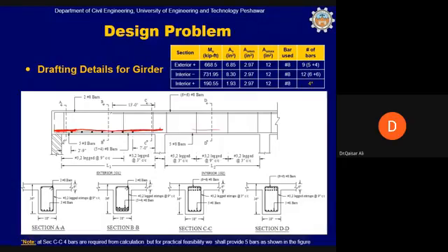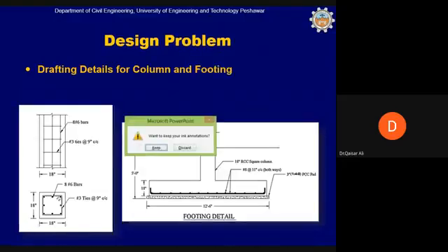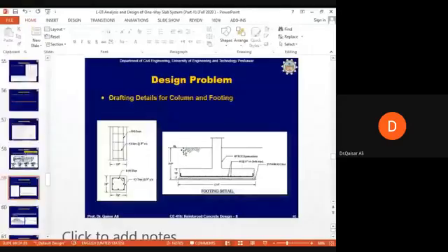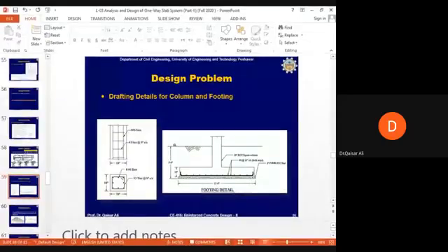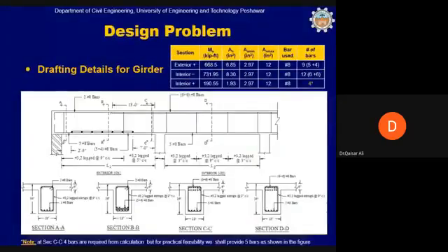of the bending moment. So if you take section BB, in section BB you can see all the positive reinforcement. You have 1, 2, 3, 4, 5, 6 plus 4, 10 bars. But in section CC, you can only see 6 bars. These 4 bars have been curtailed.